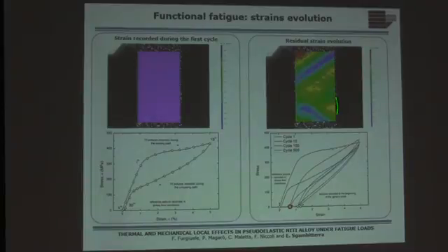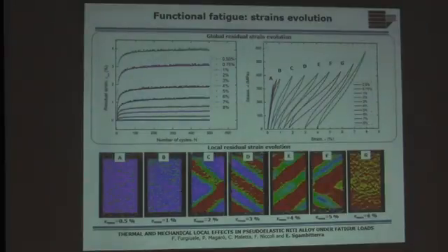After 10 cycles, there is a residual strain. This is residual martensite. After 150 cycles, the residual strain increases, but after 150, I will not expect a huge change of the material. And typically, this is what happens. So here you don't have a big change. Here you don't have a big change between 200 and 500 cycles. So this is just a main view of what happens when you want to study the stabilization of the material